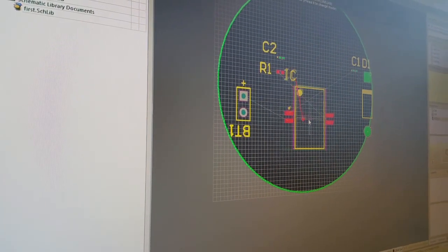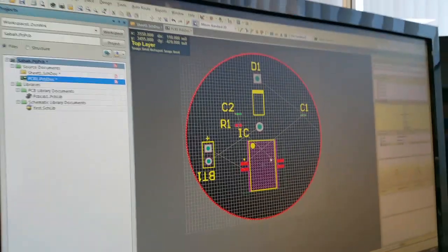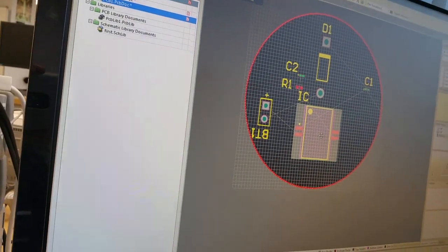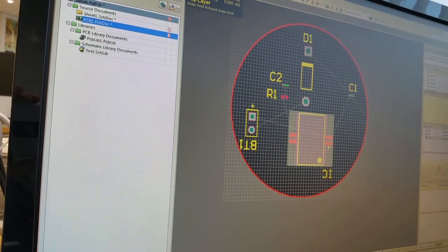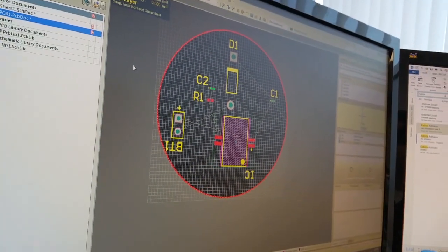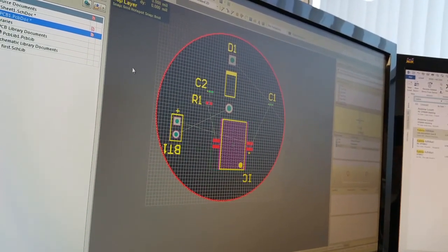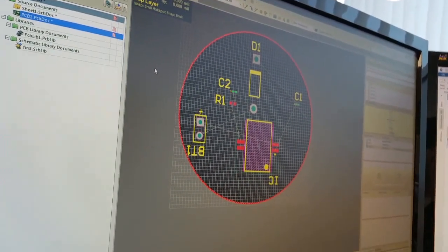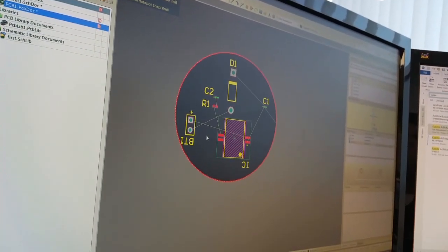So now the black one is your PCB. So come to this one, and you can rearrange everything according to this new layout. Any shape I want, I can do that. Just draw the shape. Triangle, rectangle, random. You can make it a flexible PCB. You can divide the PCB into four customized parts, this one rigid, this one flexible, customized according to the layout area you have. So now we finish it.